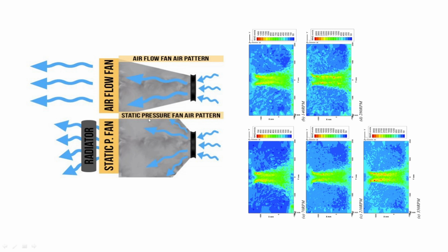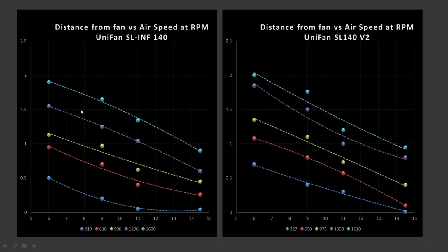But if your GPU is air-cooled, you want to make sure that there's strong airflow getting to your GPU, so you do want high-quality fans to supply it with substantial airflow. Again, this is in the circumstance that you've got the AIO or a radiator at the front of your case. And if you're using these fans in a pull configuration on that front radiator AIO type scenario, it's even more important, because the airflow pattern coming out of the fan will be identical to what we see in this sort of testing.